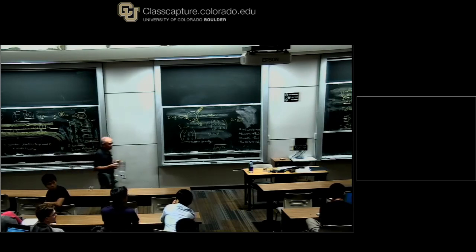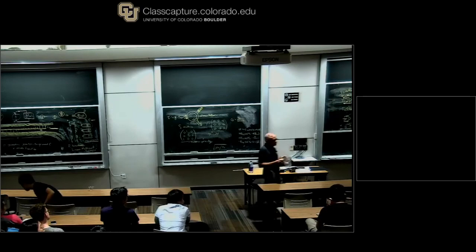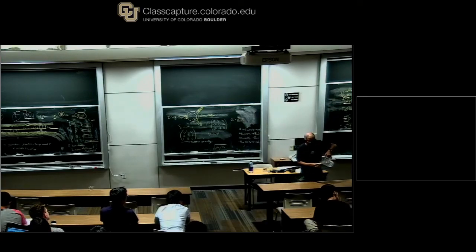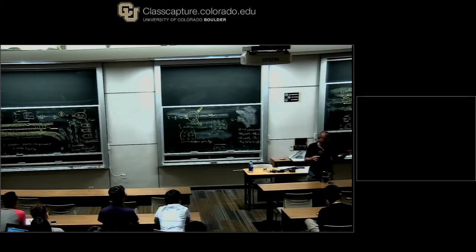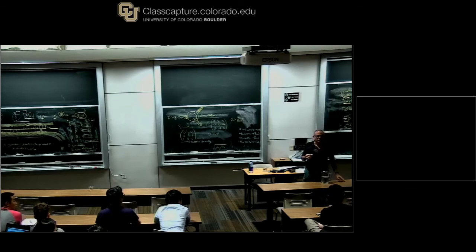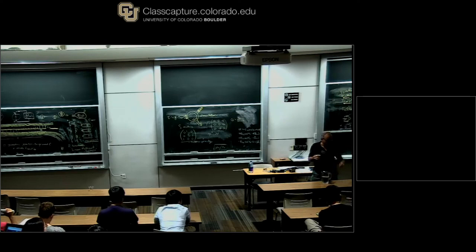Yes? So if you have some time dependence, is the black box model not valid anymore? Time dependence in the black box? Yeah. My 10-second answer is that it's right, it's not valid anymore, and I need another half hour to think about that one. How would you represent the rest of the circuit then? Well, you couldn't go to the frequency domain, for one thing. Your tools become limited, and then it depends a lot on what kind of time dependence. If you have one harmonic time dependence, then you have one set of techniques. Then you have parametric modulation techniques. More generally, I wouldn't know.